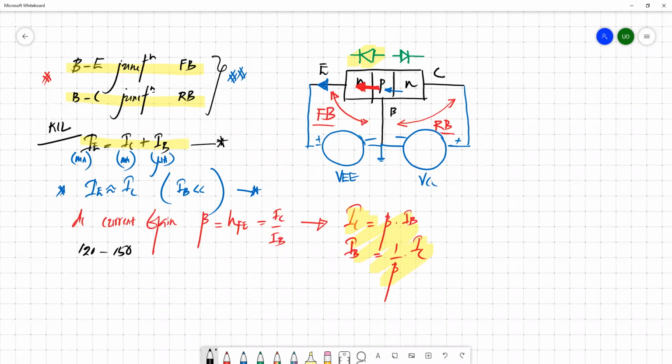If you refer to the data sheet, sometimes you can find the exact HFE or beta by looking at the graph they embedded in the data sheet for certain cases. So they may discuss this HFE with the temperature T. Then you can think of the operating temperature of the circuit, and based on that you can simply pick the exact HFE, or else you can simply choose a middle value like 130 for the safe side. If you want to go for a precise analysis, you have to use this plot given in the data sheet, and you get the exact HFE or the DC current gain for the analysis. Otherwise, you can select a nominal value in between that range, representing the overall performance.